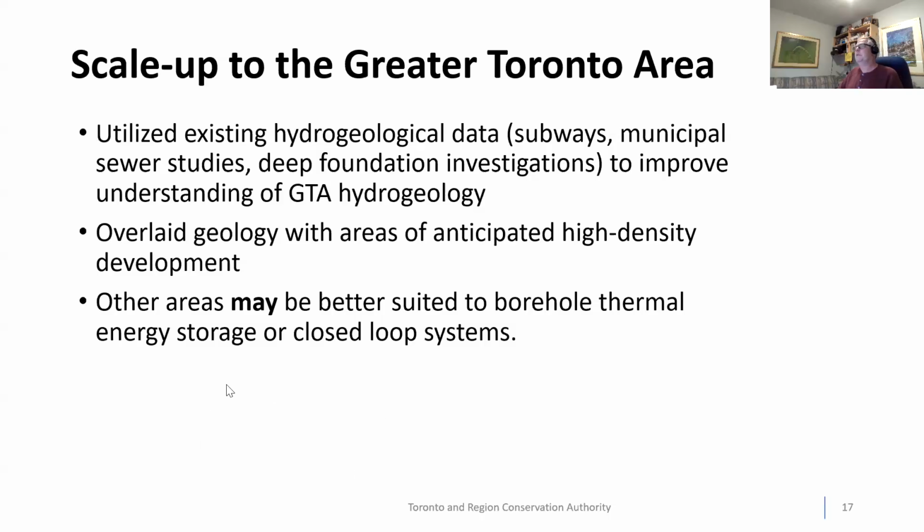So in the end, we used all the existing hydrogeological data we could get our hands on, subways, sewer studies, deep foundations, to improve our understanding of the hydrogeology. We overlaid the geology with areas of anticipated high density development: commercial, industrial, large scale residential. And we recognize that other areas may be better suited to borehole thermal energy storage or closed loop systems. And that's something that could be looked at in a future study.